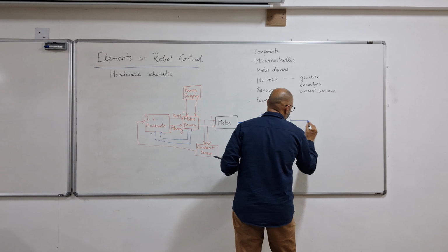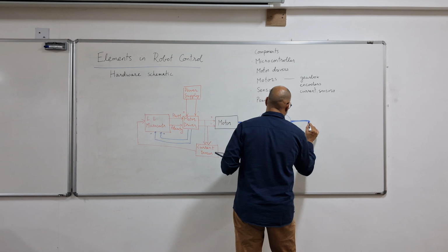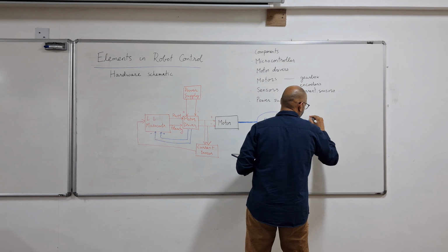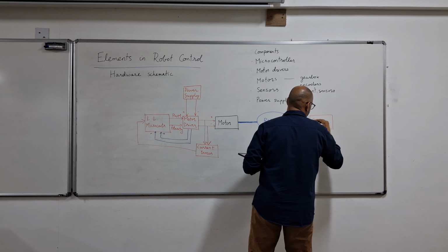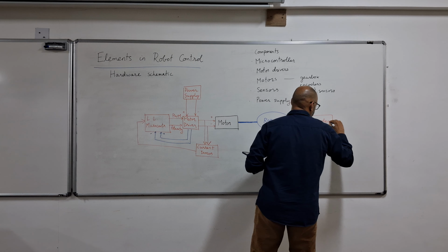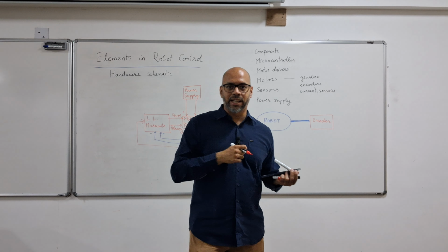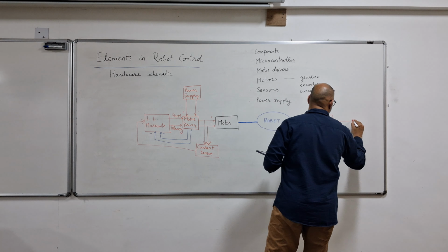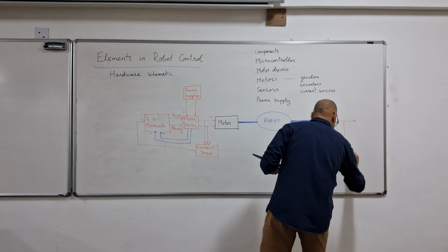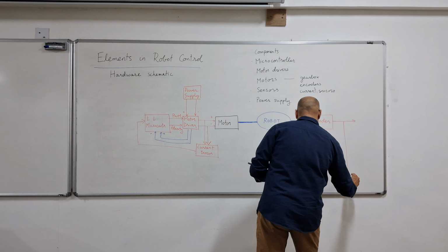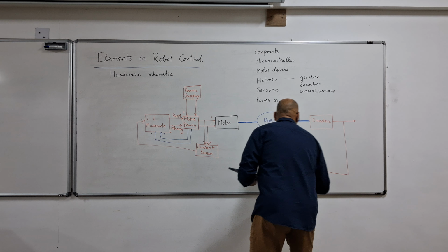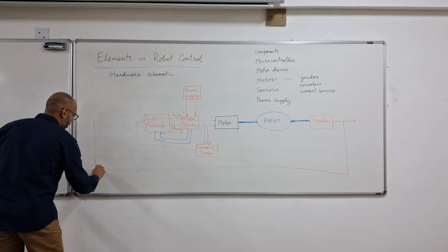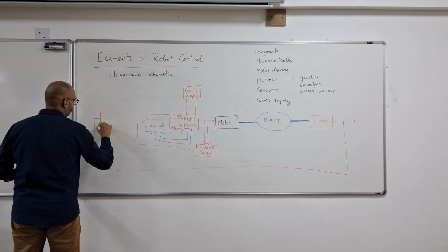This robot is again physically connected to, let's say, an encoder which is measuring all the joint angles, which in our control block diagram we called Q, the joint angles Q. So these are reading the joint angles, and this information is sensed by the encoder, and it's sent back to a higher level controller.